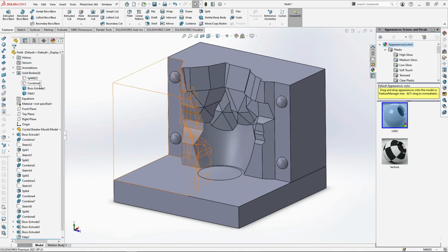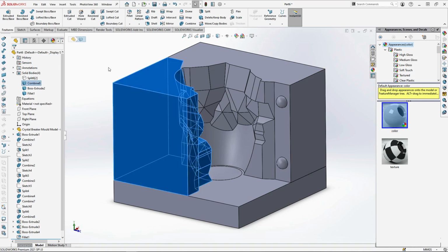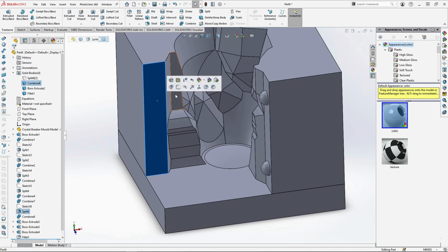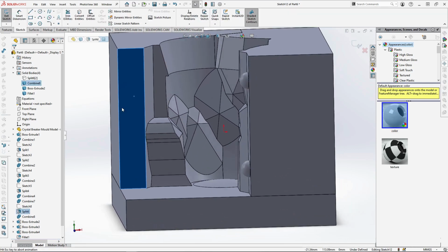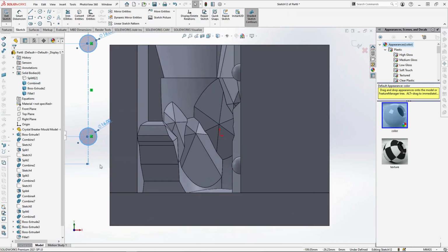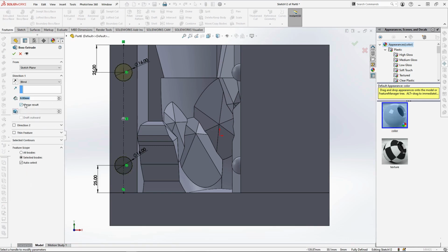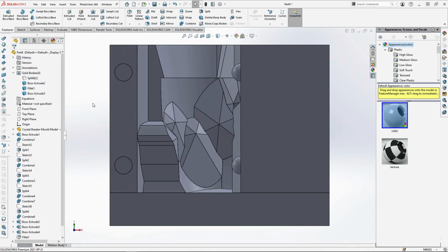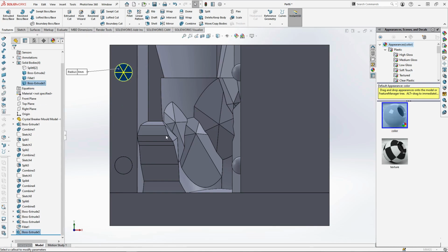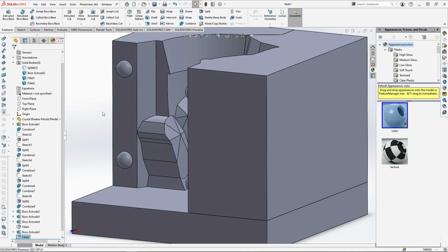Next, bring this mould part into view. Sketching onto this face, paste in the notches sketch. Fully define it with relations. Extrude the sketch by 8mm and merge it in this mould part. Fillet the faces of these notches too by 8mm.